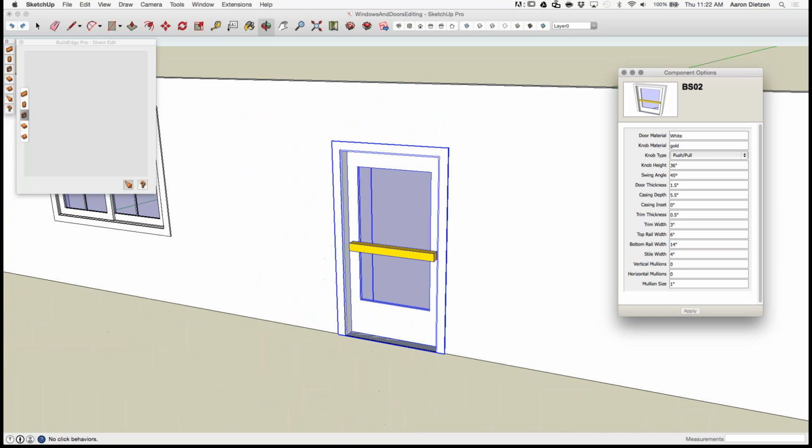I had a question come up about colors. We really just deferred to the SketchUp palette. So any color that is a named color, you can just type the name in here. If it's not a named color, if it has a number or something like that, you type that number in here and it will change it to the equivalent in your materials panel in SketchUp. This was the easiest way. Coming up with a way to import colors and all that kind of stuff was painful, so we just said, do whatever SketchUp already has set up.